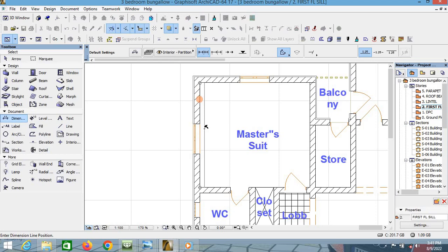Okay, you now see a hammer-like cursor appear. This hammer-like cursor is the visible line that will be showing at the intermediate points. Now, if at any place you want the dimension line to stop, you are able to move your cursor. If you are practicing along, hold your cursor and move it. Are you seeing that the line is moving? If I don't want it to be here, if I want the dimension line to be here, I can comfortably move my cursor to any area that I want it to be. If I also want it to go out of the wall, which is not reasonable because this is an internal dimensioning, I can move my cursor. Okay, let me stop it here.